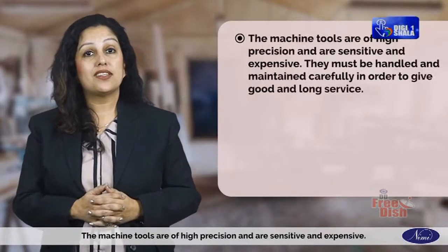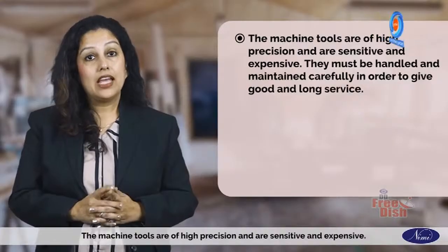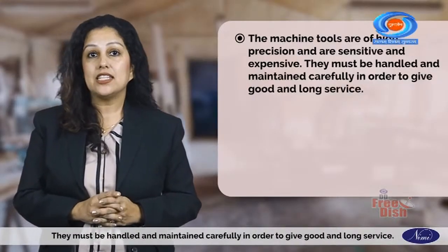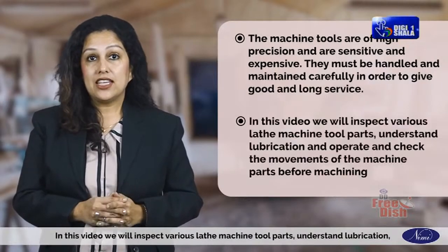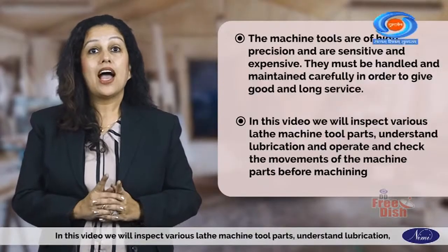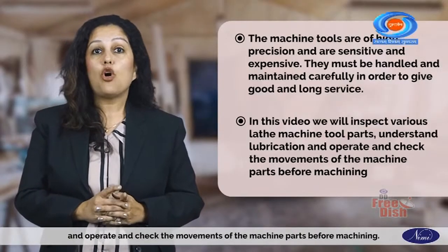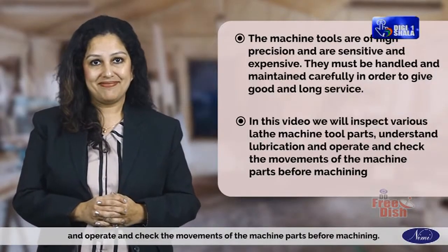The machine tools are of high precision and are sensitive and expensive. They must be handled and maintained carefully in order to give good and long service. In this video, we will inspect various lathe machine tool parts, understand lubrication, and operate and check the movements of the machine parts before machining.